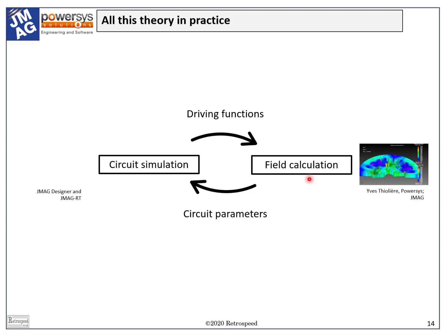There are, of course, second-order effects which I have not covered here. For example, the effect of spatial harmonics on the variation of LD and LQ, and in the induction motor, the whole question of determining the rotor currents which are driven by electromagnetic induction and not by a current-controlled PWM inverter.